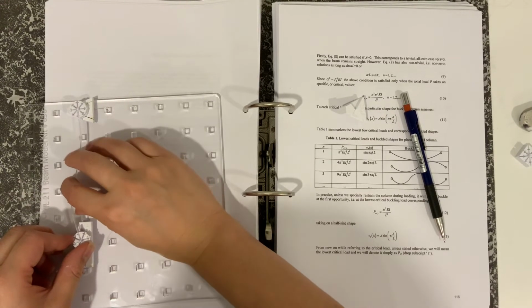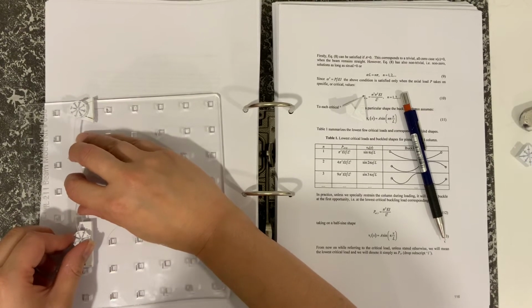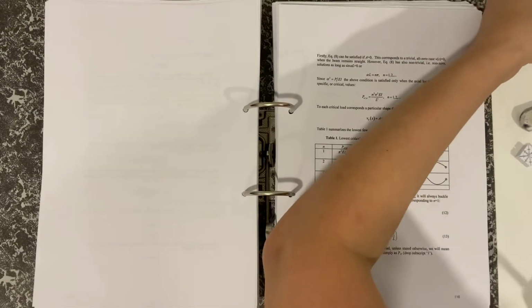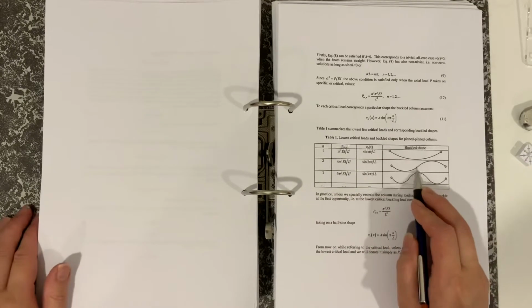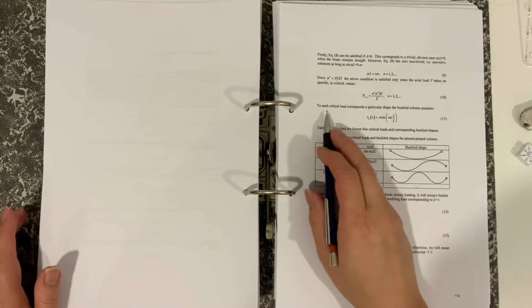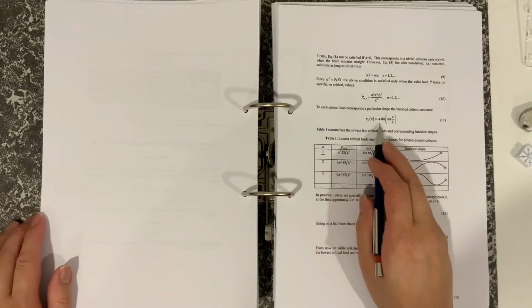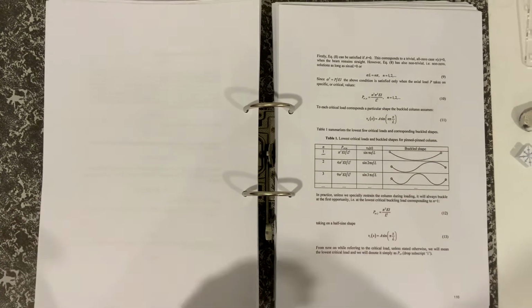And if it was 3, I wouldn't be able to show that, but if it was 3, maybe it would be 3 half sine waves. Okay, so it's always going to buckle into the lowest mode, and unless there's a restraint at that position, then it's just going to be n of 1. So to each critical load corresponds a particular solution, which is sine n pi x over L.